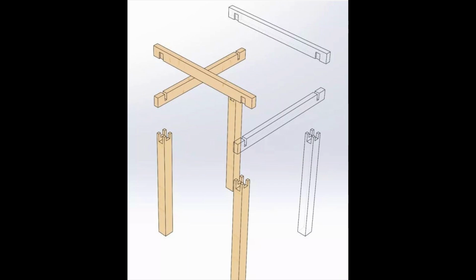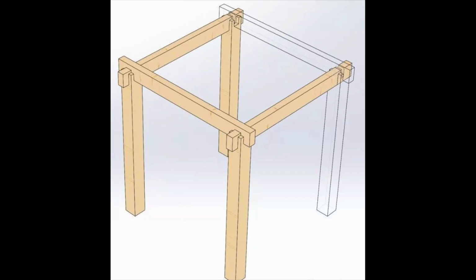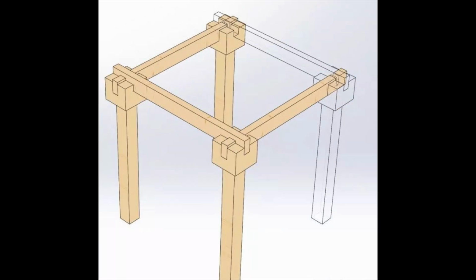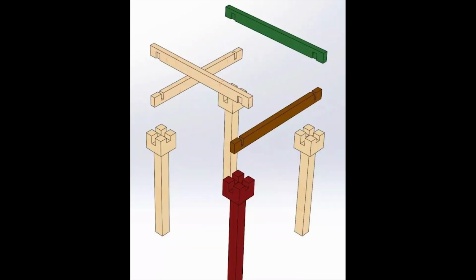This picture is a picture of the disassembly of the column and the beam openings in different directions. This is the reassembled picture. The freedom of the column is reduced by adding constraints in 2 directions, making it impossible to slide at will. However, after the groove is opened, whether it is the end of the column or the position of the beam opening, the material's stress performance is affected by the opening, so the ancient Chinese came up with the idea of using the material wasted by the opening to add it to the part where the beam and column are connected to deal with tension, pressure, and shear. This is a picture of the disassembly after local reinforcement.